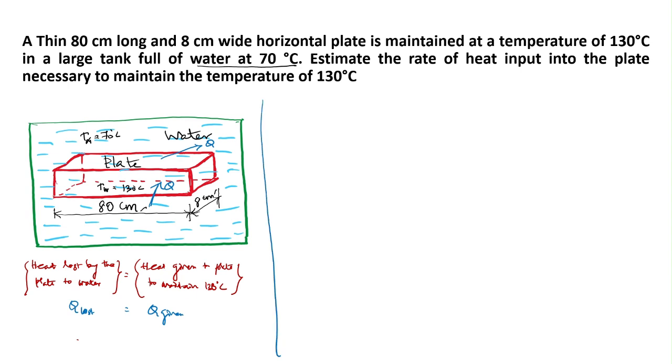Before proceeding with the problem, you must know the problem type. The first case is free convection. You already know this because the velocity is not given. The second case is external flow, because no fluid is flowing inside the plate or inside a cylinder. Third, you are going to find whether the flow is laminar or turbulent.